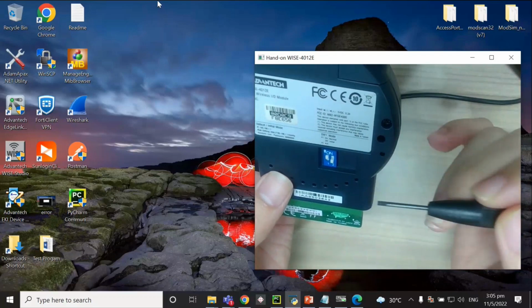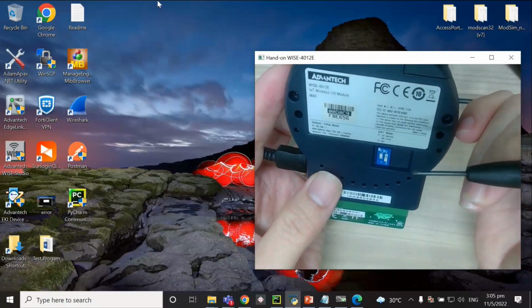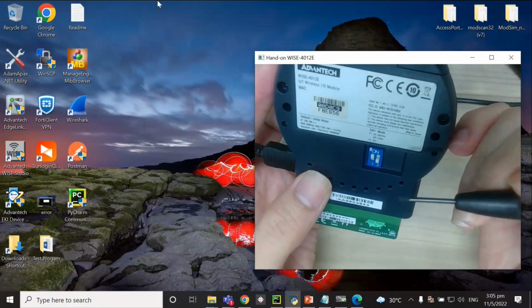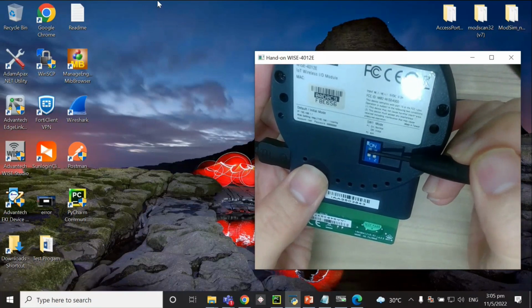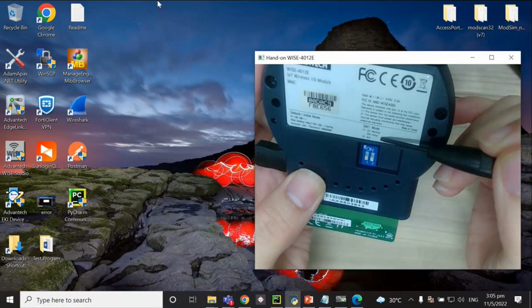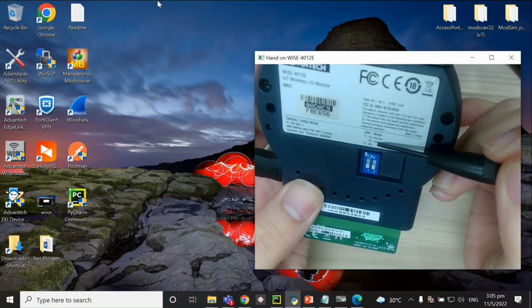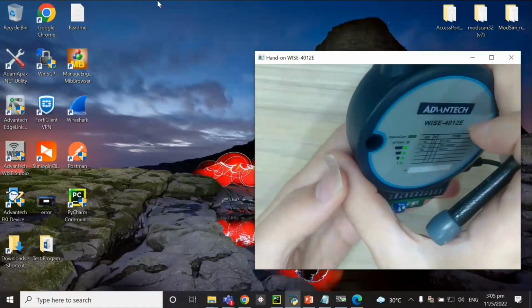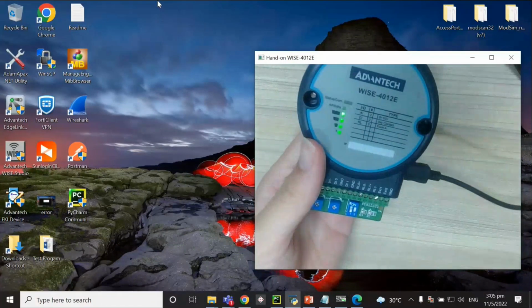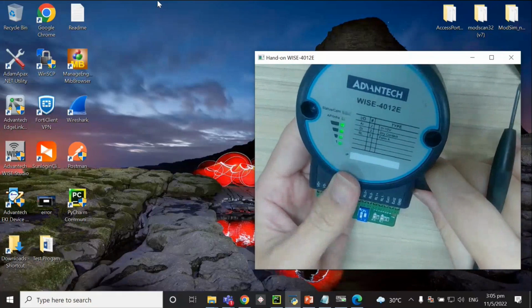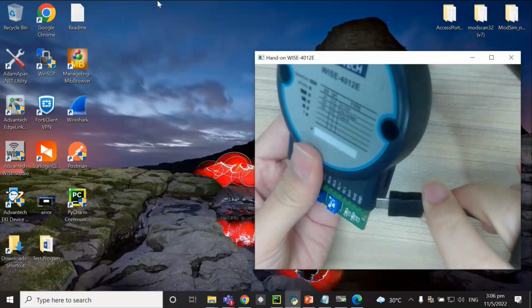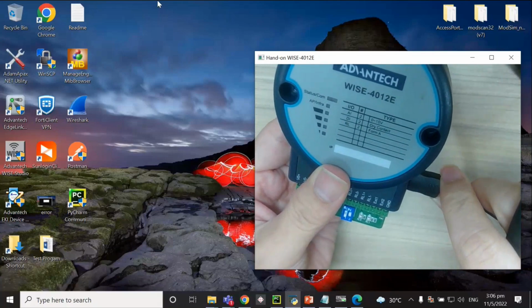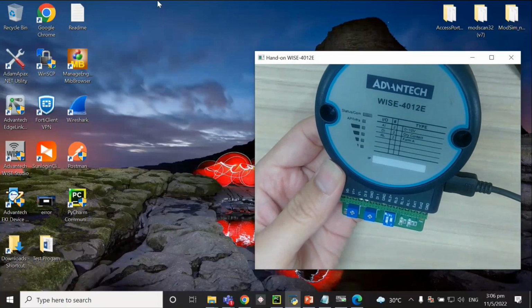This is one of the important things when you do the configuration. Let's say we want to use the AP mode. I just switch it off. Off is the initial mode, we call it AP mode. Whatever changes you make, you have to recycle your hardware. So I just remove the USB cable and connect it back. You will see the difference.